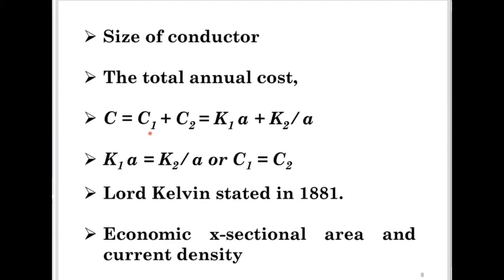And then what else do we need to know to determine the resistance? Cross-sectional area and diameter, they are related. It's also correct. If you know the diameter, you can calculate the cross-sectional area. Constant of resistivity? It's not called constant of resistivity. It's resistivity. The resistivity of the material that we used to make that conductor, and the length, that is correct.